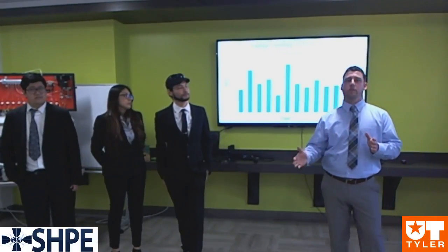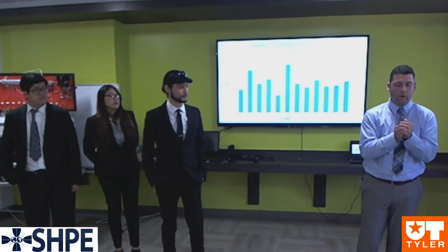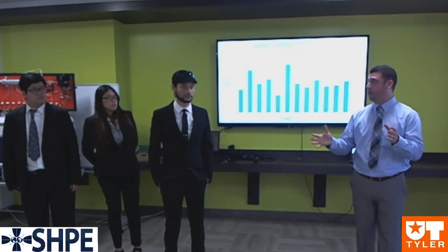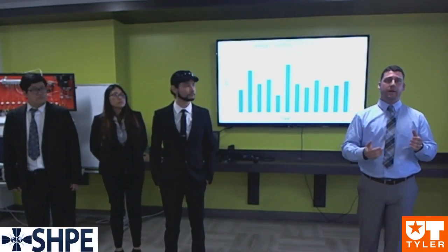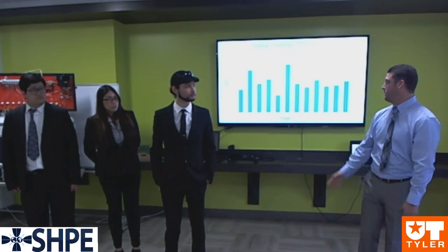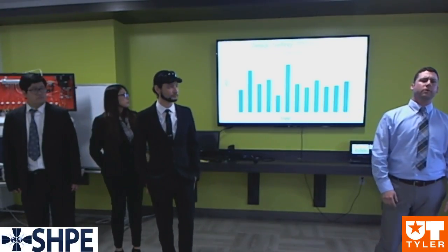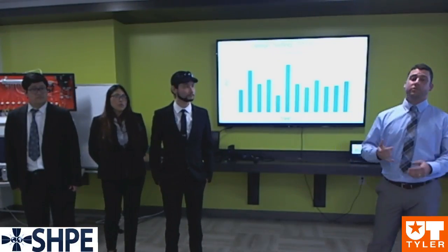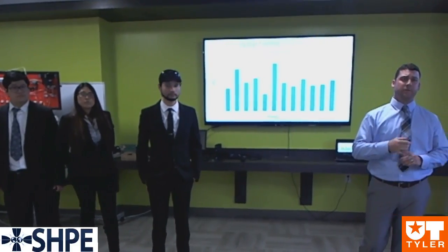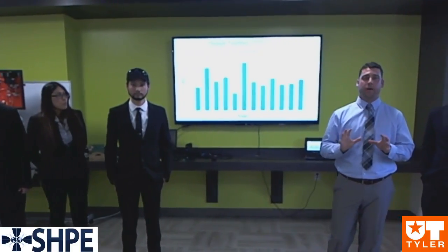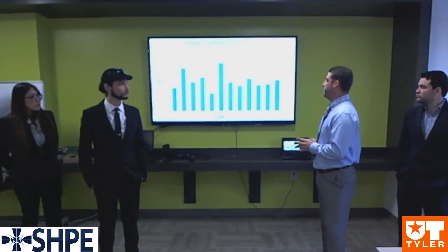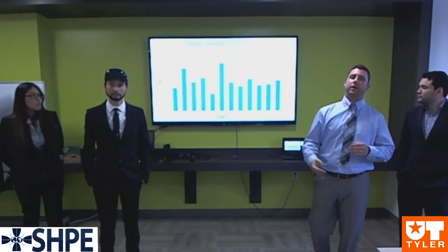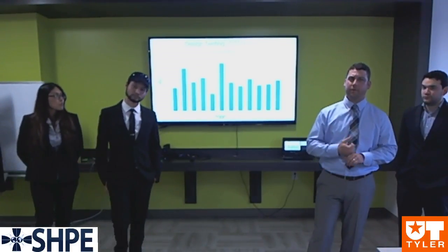The additional samples, so you don't just have one neutral sample. You have four, right? If I walked in as a researcher and saw one that was low, I'd wonder what's going on with that one. Maybe I do have an obstruction somewhere that's throwing it off. Maybe my air supply is somehow bad. Maybe there's a leak in it somehow. I'm not sure, but it would raise a red flag. That's why you're consistently monitoring your data and say, hey, maybe I need to fix that one. Or maybe you have a bad sensor.